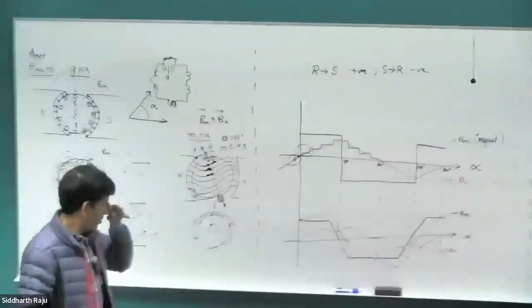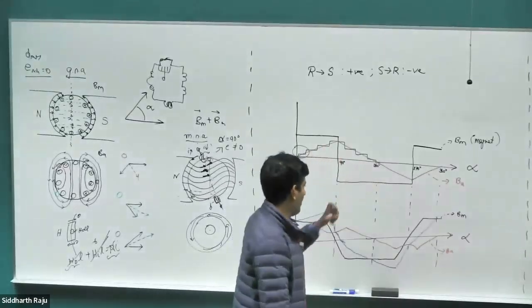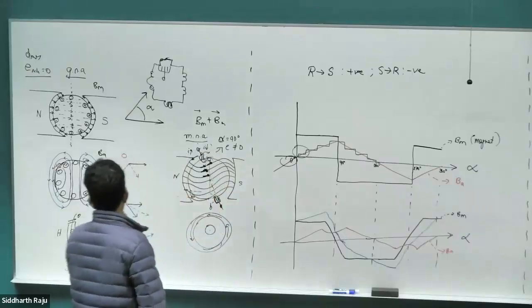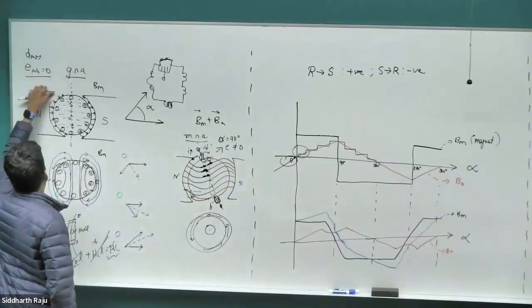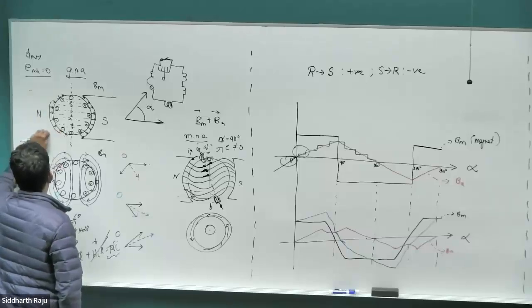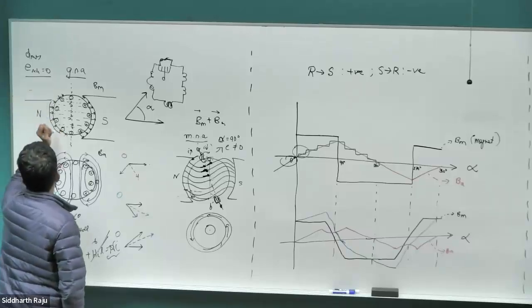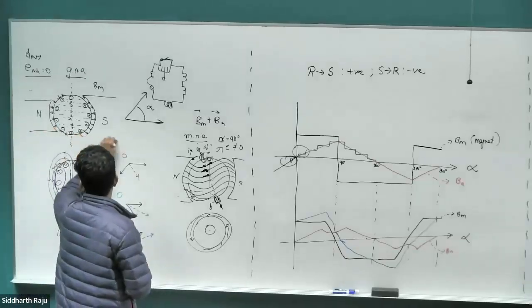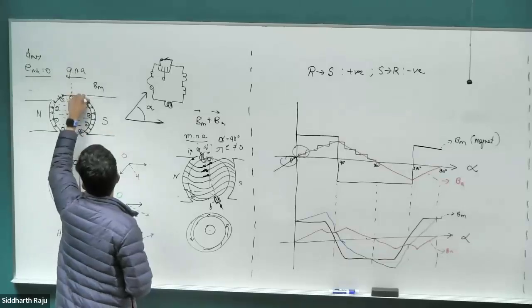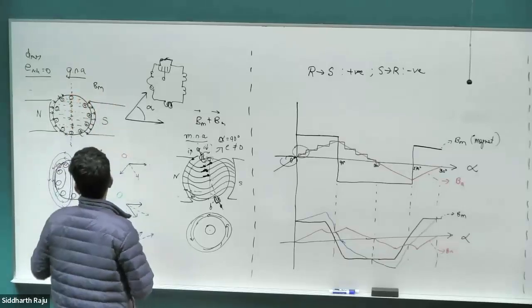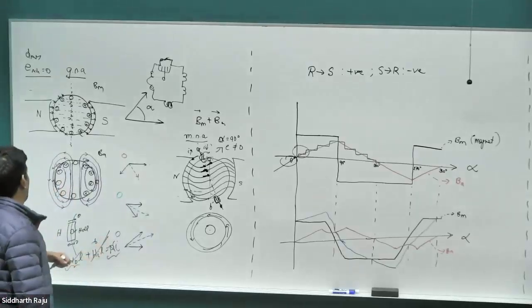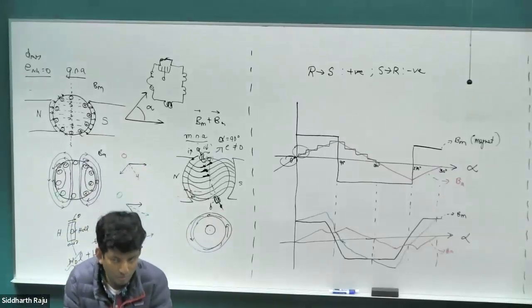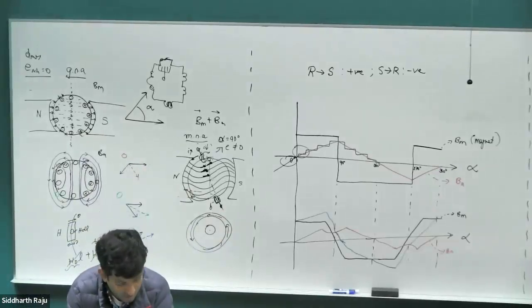So let's come back to our model here. This is what we have. In a practical motor, we won't have the magnet do a full coverage of 180 degrees. We will rather cut it short so that the pitch of the magnet is lower than 180 degrees, typically around 120 degree pitch, as I showed you last class, or even the motor that we have in our labs. What was the purpose of doing this? There are two things that we are trying to achieve by doing that.